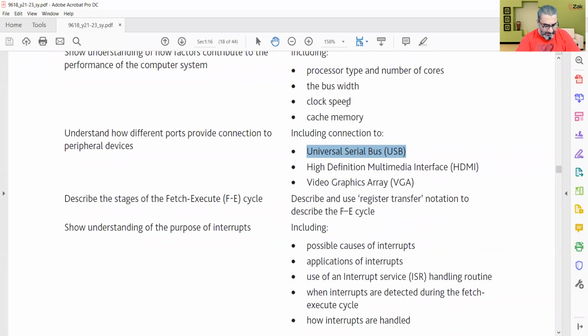When the device is plugged in, like my cell phone, I just showed it to you, into a computer using one of the USB ports, the computer automatically detects the device that is present. This is due to the small change in the voltage level on the data signal wire in the cable. The voltage over that wire gets changed, and from that change the computer senses which device it is. The device is then automatically recognized by the operating system, and the appropriate device driver is loaded so that computer and device can properly communicate.